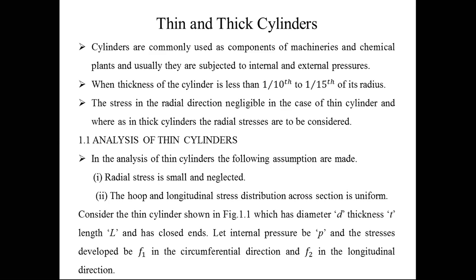The stress in the radial direction is negligible in thin cylinders. When the thickness is more than 1/10 to 1/15 of the radius, that is called a thick cylinder. Coming to thin cylinders, in the analysis of thin cylinders, we are assuming two points. One is radial stress is very small and it is negligible in thin cylinders.